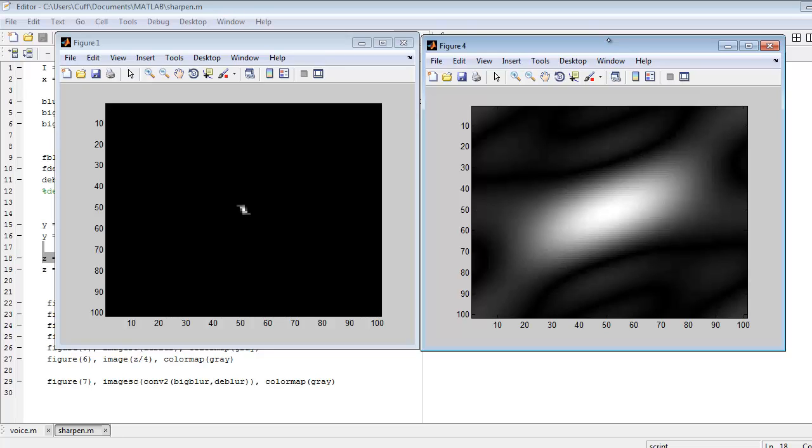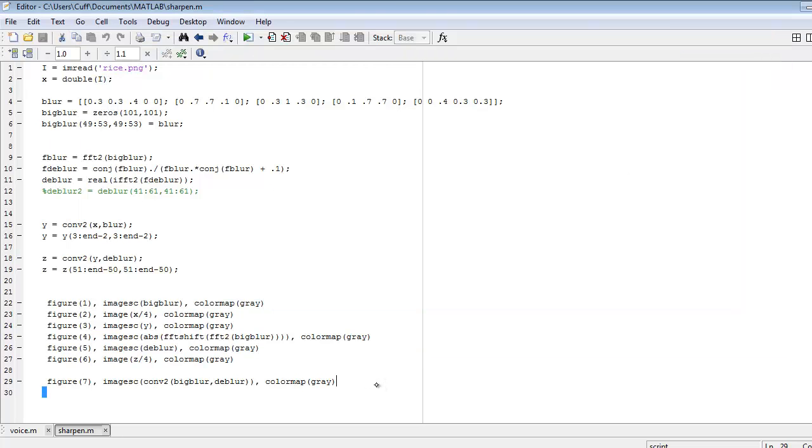Is it clear why I'm saying that? Because convolving with an impulse response is multiplication with the Fourier transform. And this is the magnitude, the absolute value of the two-dimensional Fourier transform of that impulse response. So what I'm going to want to do is boost up the high frequencies to get them back in the deblurred image. I do something that's barely more complicated than simply taking the inverse, 1 over that Fourier transform.